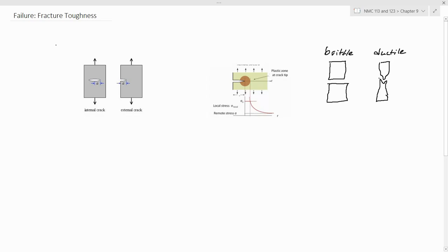It may be micro voids or it may be macro voids, but there will always be voids, and those voids, those edges within the steel, create a level of stress concentration. So you might find that the material has an internal crack, like the one being represented here, right? Now around the crack there is a specific stress concentration.